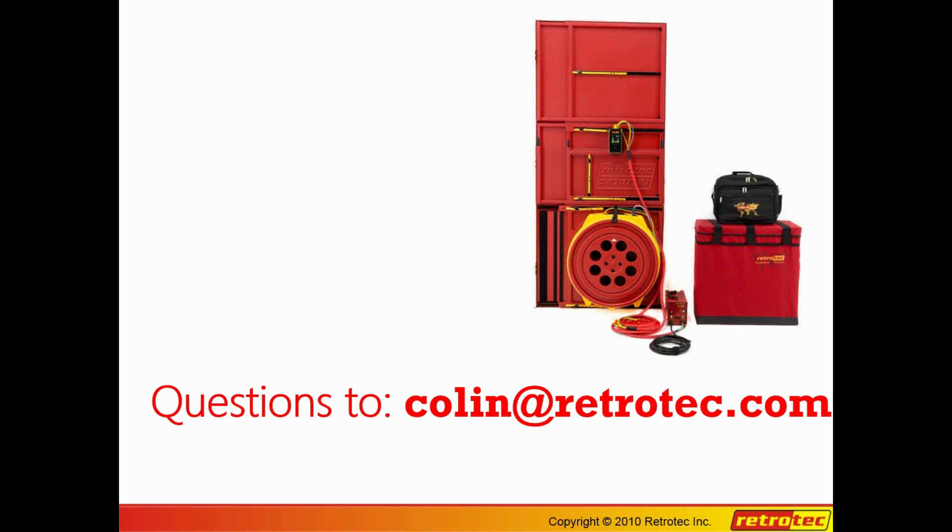Someone was asking, if we're not using a second blower, can we choose to use sealant for the ceiling panel instead of plastic on the ceiling? I think what you're saying is, can you actually seal the tiles in place? It's actually relatively difficult to do. It is possible to caulk every tile in place, but if they're not well sealed, that little itty-bitty crack around the tile is enough to make the enclosure fail. But you could theoretically caulk every tile to the suspended ceiling and actually seal the ceiling in place. That would be possible.